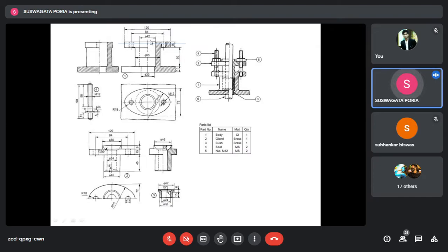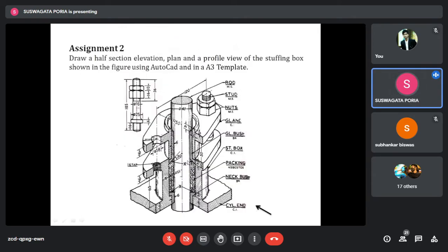The shaft dia would be near about 40. Okay, so that will be here. A 40 dia shaft can be used in the stuffing box. Not 40, sorry. Here is 33. So it should be 30. The shaft dia, you have to pass through this 33 neck boss. So this is another diameter. This is 33. This is 33. And it will have to go with it. You have to draw all these parts for the drawing here.